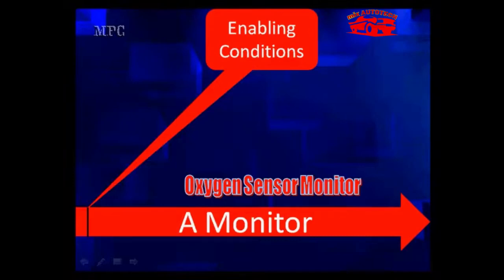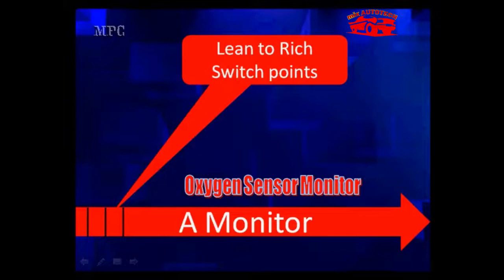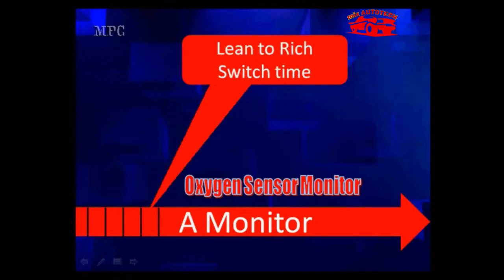The first thing, we're going to be in the proper enabling conditions. Then we're going to look for stuck rich or stuck lean faults. This is very simple: oxygen sensor voltage too high, too low, doesn't move. Then we're going to have to measure the switch points. Where is this thing switching? And we're going to talk about and define exactly what a switch point is. We're going to look at rich to lean as well as lean to rich.